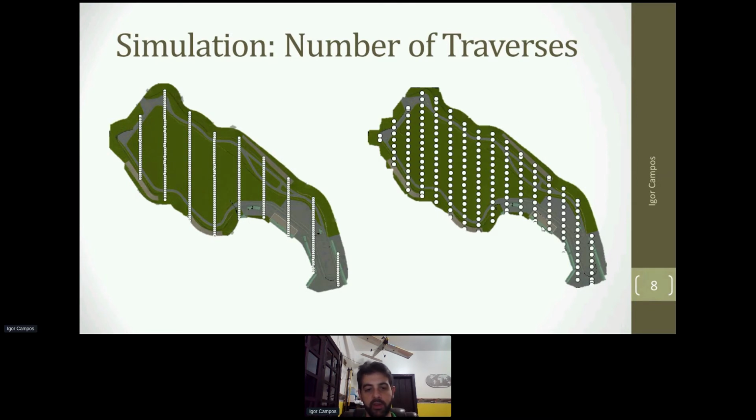In this survey, it was 3 positions. So it would take a picture to the left, a nadir picture, and a picture to the right. Both pictures that are pointing down would be within the specified front lap, just as in the nadir survey.